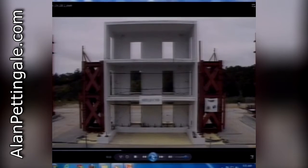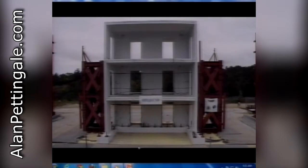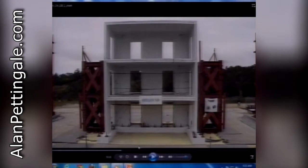You see that? These are reinforced masonry shear walls, and there's lots of reinforcement, way more than what we would use in a structure in Texas. And you will see that this middle wall, all the reinforcement fractured, as we figured out later, and it just slides back and forth on the foundation, while these two T-walls at the end of the structure develop big shear cracks that are very dangerous for the building.